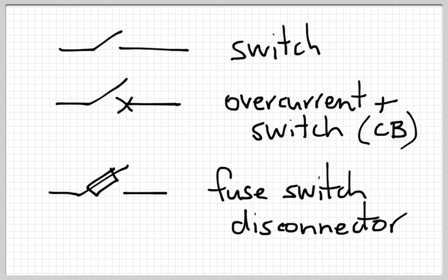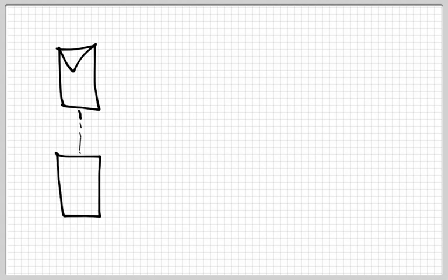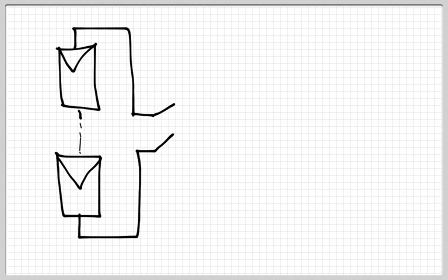So let's put these together and draw a PV system. So the PV system consists of a module, well, usually many modules, so for shorthand, so that's known as a string of modules, which are then connected to some form of isolation device. Where that is depends on what you're doing, and that's connected to the input to an inverter.